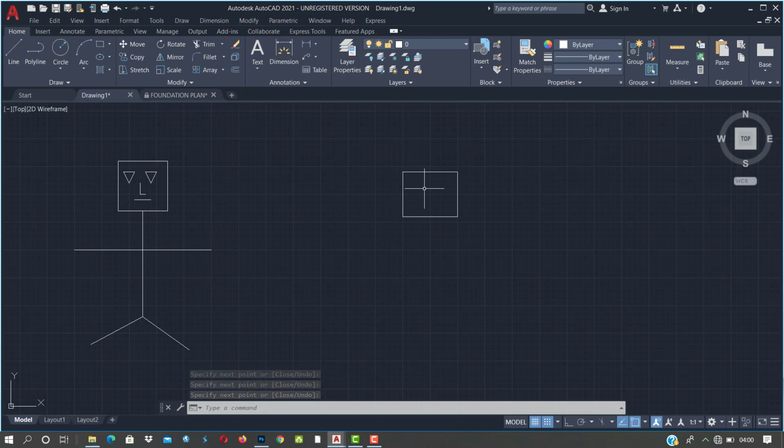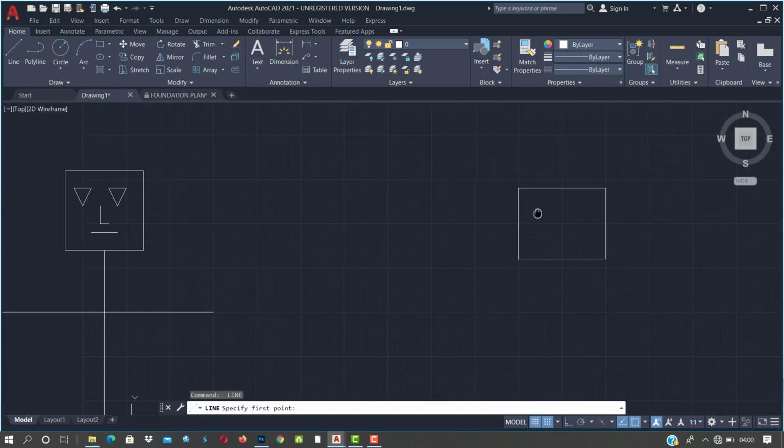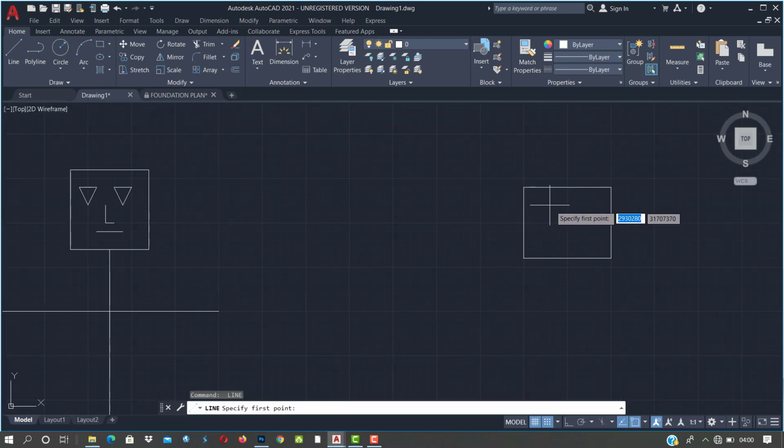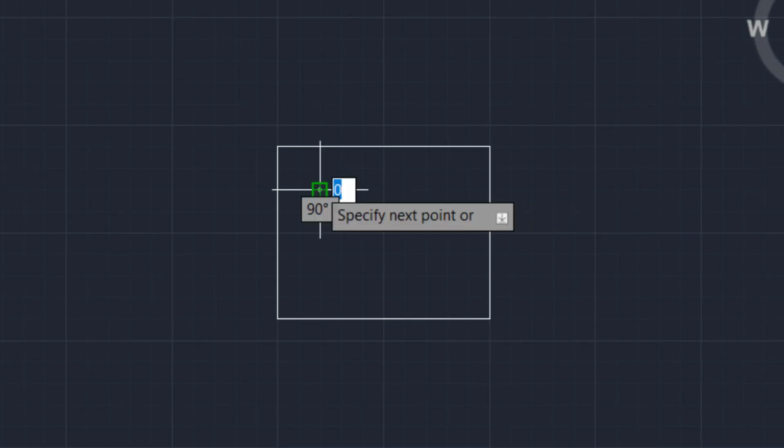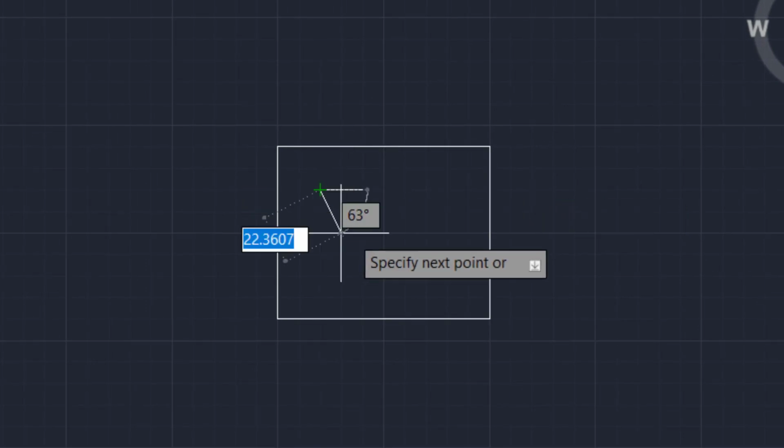Now let's try and draw the eyes. To activate the line command again, since what you've already done, just press spacebar to activate it again, so the line command generates again. For AutoCAD, spacebar and escape are going to be your best friends, so take note of that. So let's draw the eyes. AutoCAD says specify first point, so let's specify it. Then the next point.